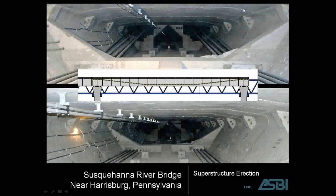That facilitates the squeeze out of the epoxy, which you can see here at the joint of the segment. You can see some epoxy that has come out of the joint, which is good. Squeeze out is what you want to see. This also shows the layout of the permanent post-tensioning.